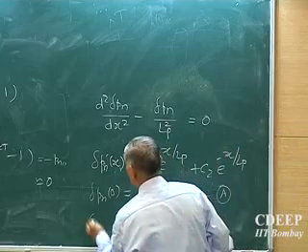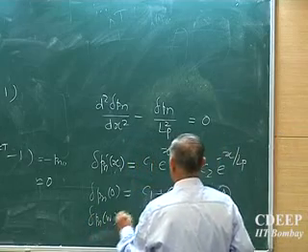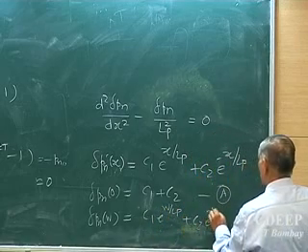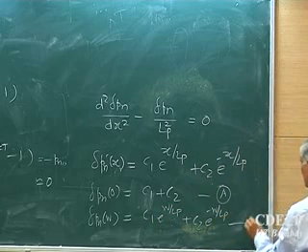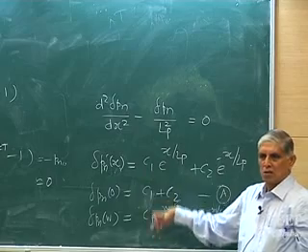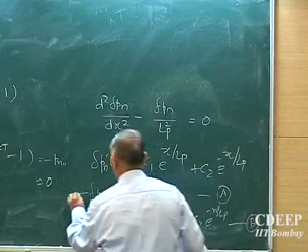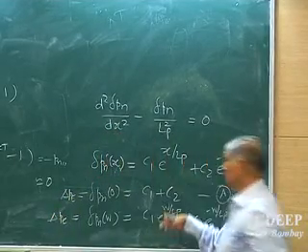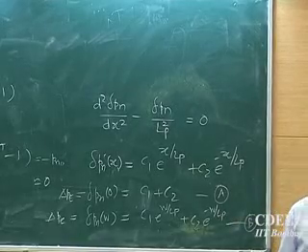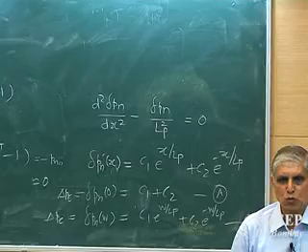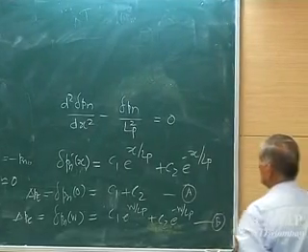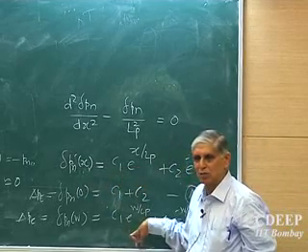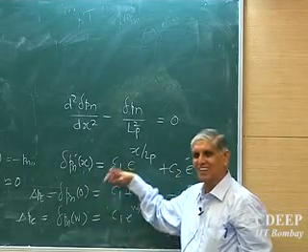And if I put x equal to W, it is C1 e to the power W by LP plus C2 e to the power minus W by LP. This is equation B. Two equations, two unknowns, and these values are delta PE and delta PC, which are known. Solve A and B simultaneously, or take C1 equal to delta P minus C2, substitute here, get the value of C1, resubstitute, get the value of C2.